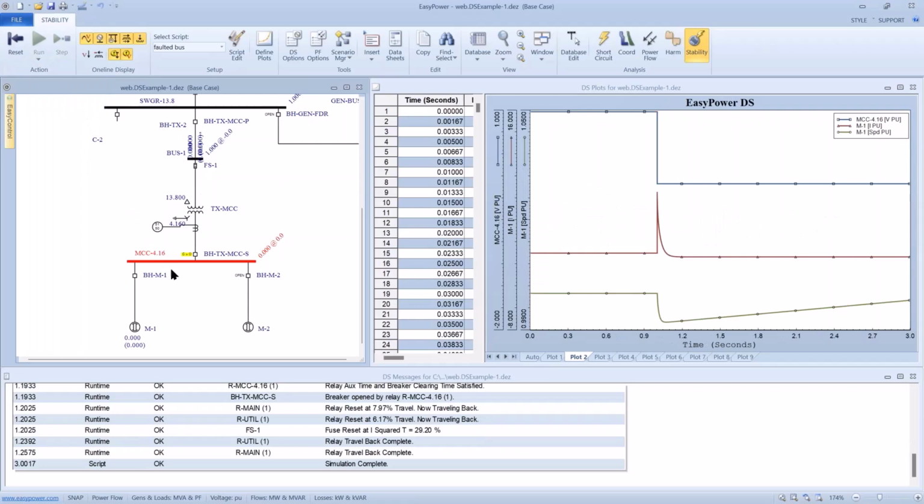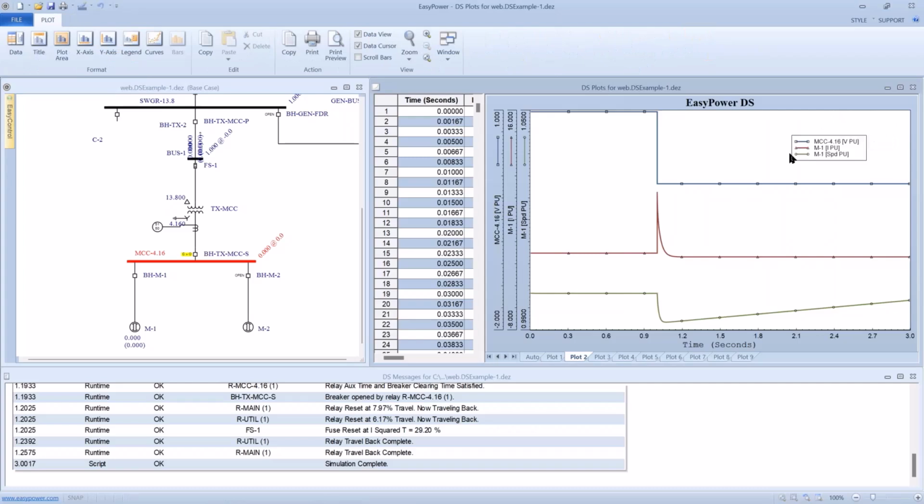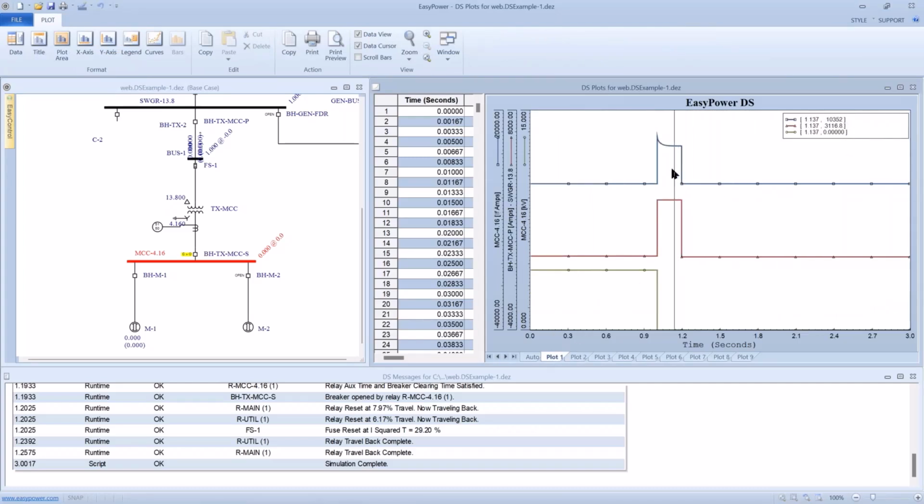and what we see is that at the end of the simulation, this bus is offline, and for some period of time, we're plotting bus 2. Let's plot bus 1. So this is the energy that's being consumed during the arc flash. The first trace is the current on that bus into that fault. The second trace is the current in the upstream transformer. And then the fourth is the voltage on the faulting bus.